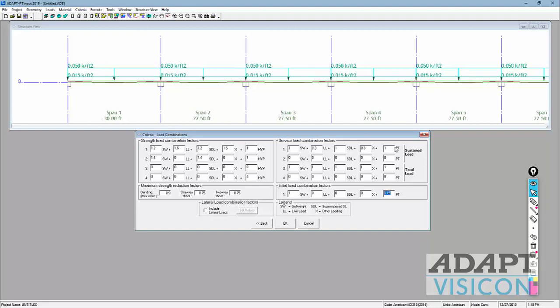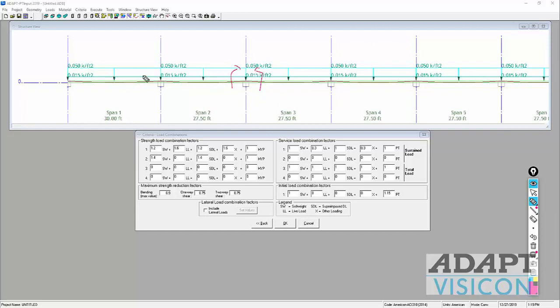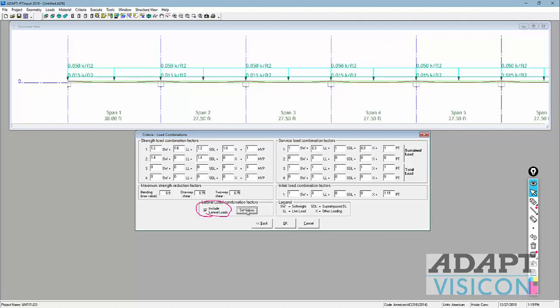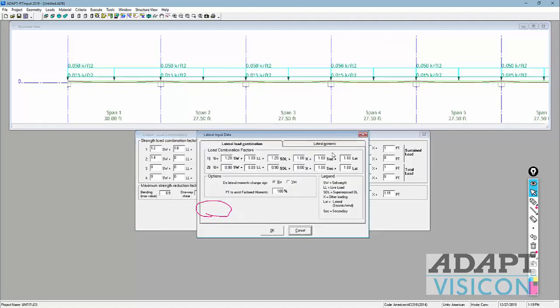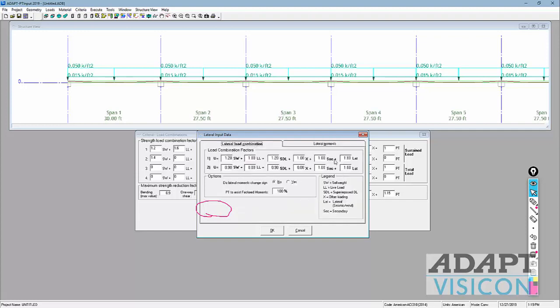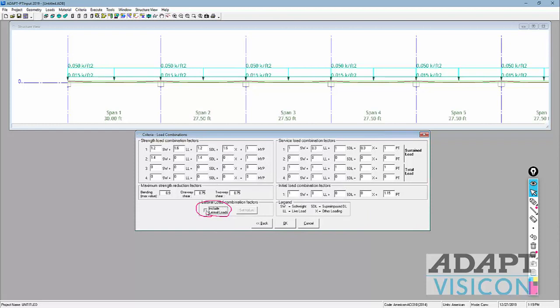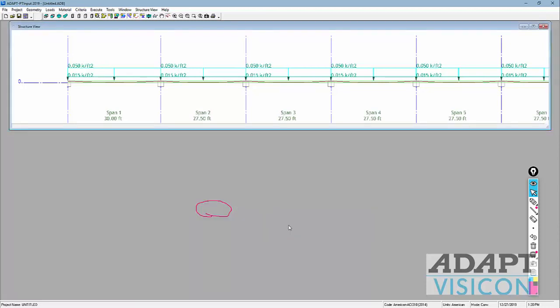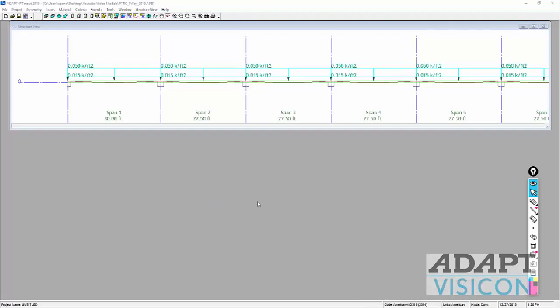You can also, if you needed to, include joint moments at the joints, if this was a frame, for example, a moment frame, and you were designing it also for lateral moments. This really applies more to beams, I think, but we could include lateral joint moments here and also additional combinations including those lateral moments. So the moments are input in this table. The combinations are then dictated here. Okay, we're going to leave lateral off for this example. I'll go ahead and select OK, and I'm going to save the model. Okay, now that the model is saved, we're going to execute the model.